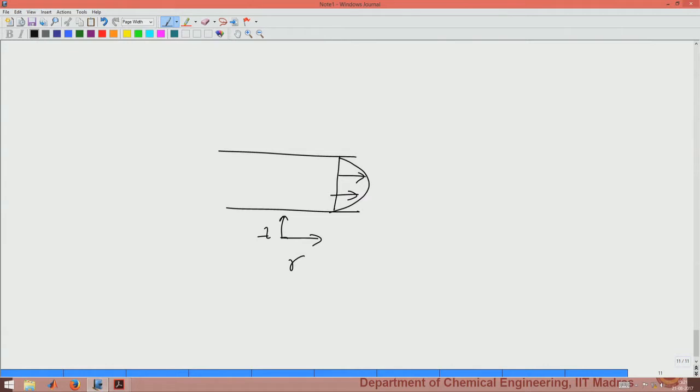So, based on the rheometric experiment that we are doing, we will always first need to identify whether this is a shear flow or shear free flow or a combination, and more importantly, we will at times have to understand the fluid mechanics of the flow. Under what condition does it make sense for me to write a velocity profile like this?